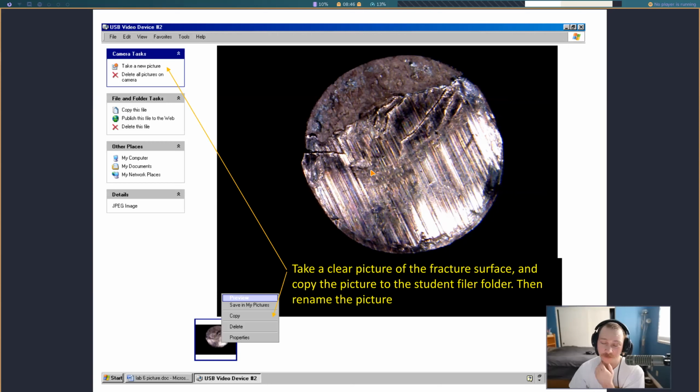And you'll see for a more ductile material, it's going to smear quite a lot. This looks like it's copper, so you see that it's smearing a lot, because as we're applying this shear force down, if it's a really ductile material, it's not going to fracture right away, so it's going to smear quite a lot. But if we have a more brittle material, it's not going to withstand that force as well, so it's not going to smear quite as much.